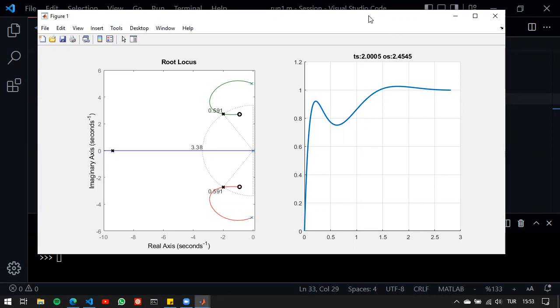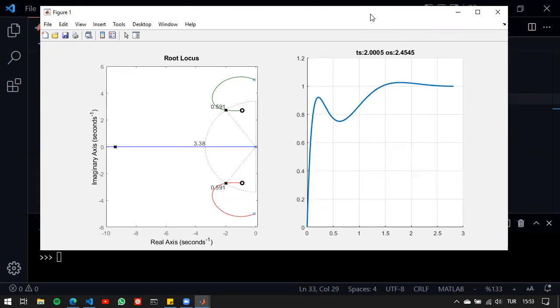Now, in terms of PID controller design, it seems a little bit odd because we have a set of zeros in the dominant region. And then we have our set of complex conjugate poles that should be dominating, and then we have another pole. In terms of dominance factor, it seems like this one does well, but we have these two zeros here.